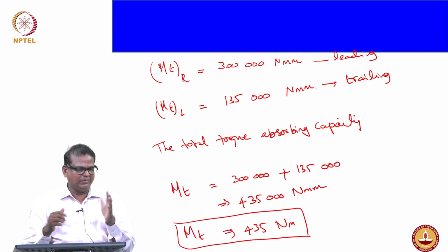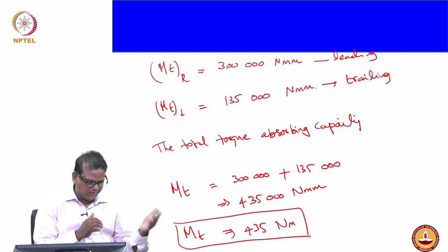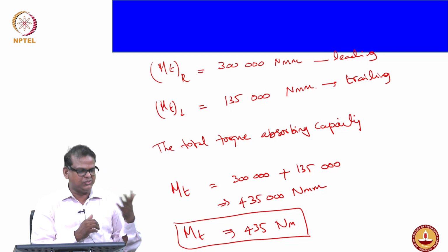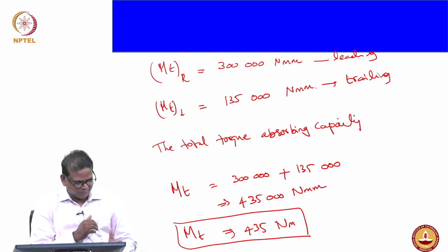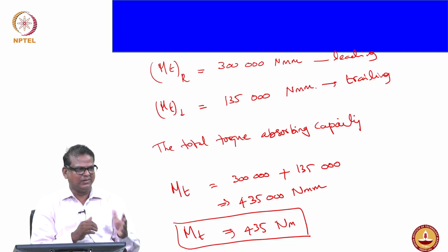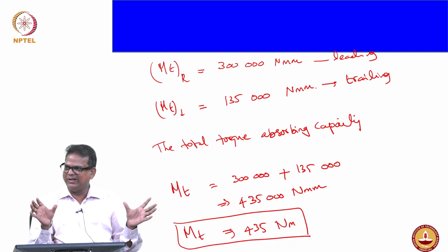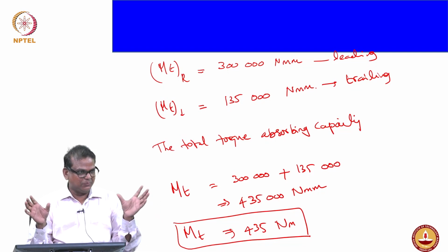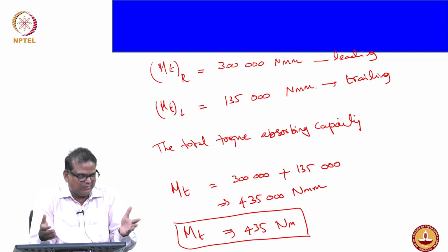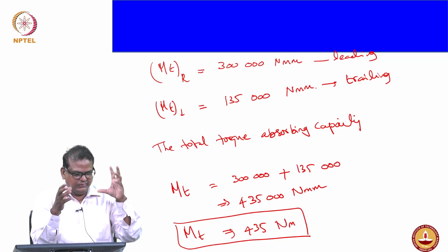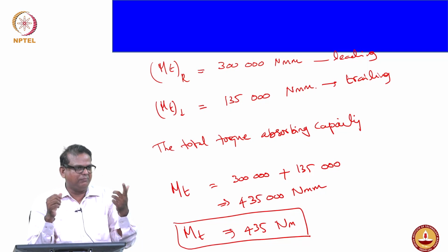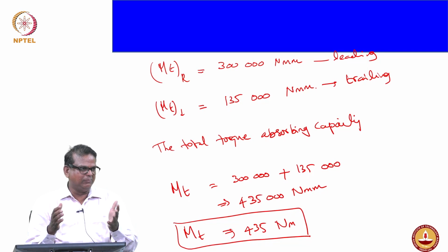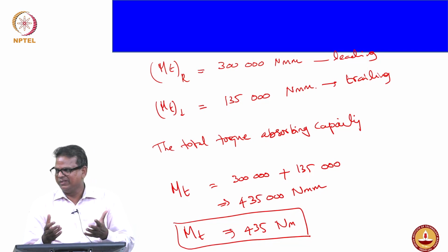So when pressure changes, obviously the corresponding moment of normal force and moment of friction will change. Because of that, the torque also will change. Now do you understand how the leading and trailing shoe function? Another thing: instead of having the trailing shoe, if you replace it with a leading shoe, then the braking effort will be much better, more effective.